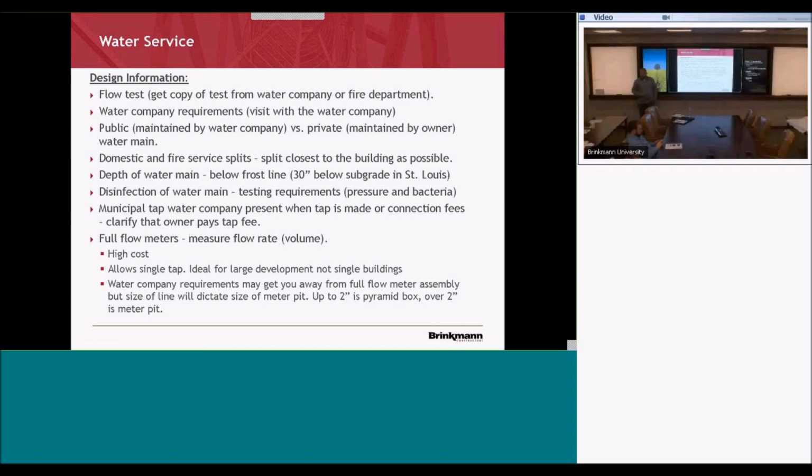What's the typical range, or what does that tell us? Those numbers are nice, but I don't know how we know if we need a flow test. You always need a flow test. Well, how do you know if it needs a fire pump? Well, your sprinkler contractor, you can call and talk numbers with him. He can tell you real fast if you've got a problem or not.